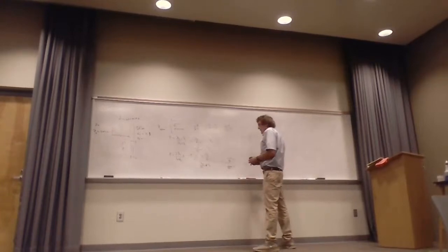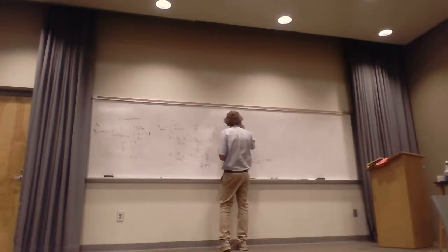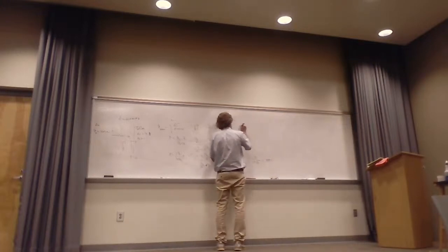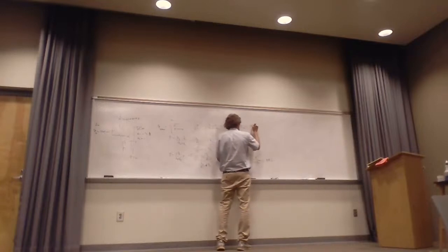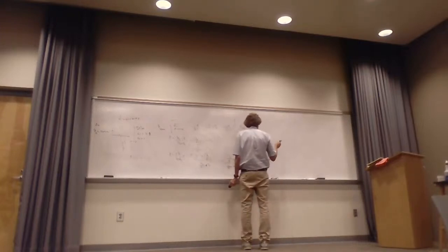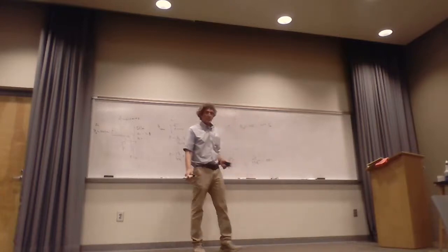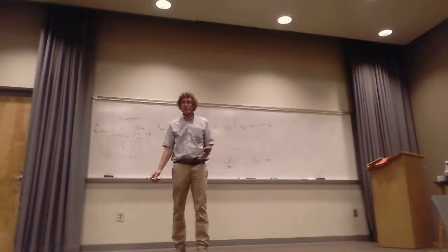Okay. Now, if you got the transmission coefficient, that means the E field in the Teflon, I'll just call it the transmitted E field, is this transmission coefficient times the incident E field. The incident E field is 1 volt per meter, so 0.82 volts per meter would be the magnitude of the E field in the Teflon. Do you all agree with that?